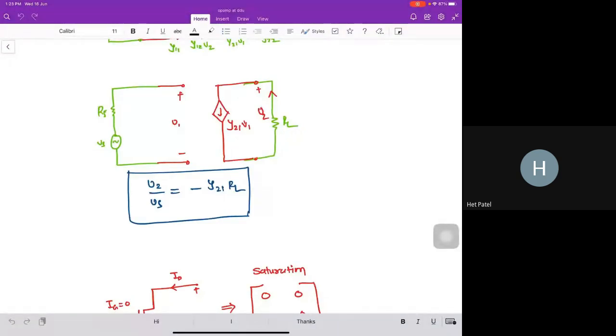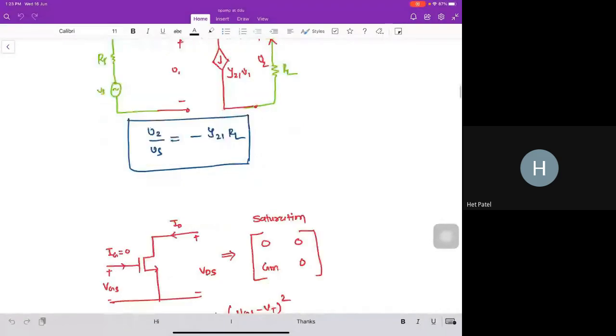So till now, what I told is the DC power I want to convert at the specific frequency. This can only happen with the nonlinear devices, but the nonlinear devices, the analysis is tough. So I have to approximate it to the linear one, and the linear one I have derived the y parameter matrix, and I am looking for the devices. Which device is giving me this y parameter network, right? So let's look at the devices.